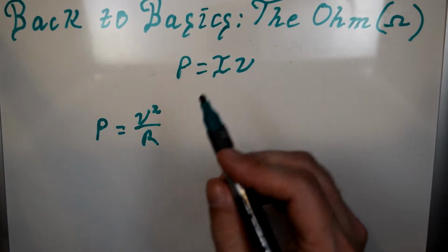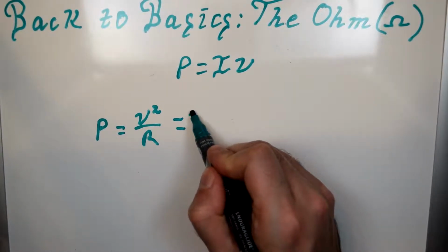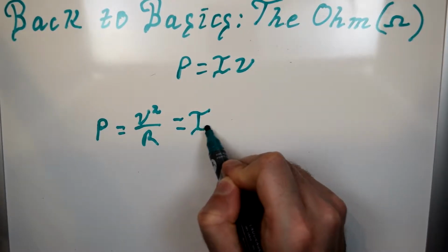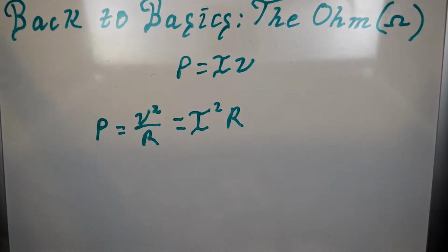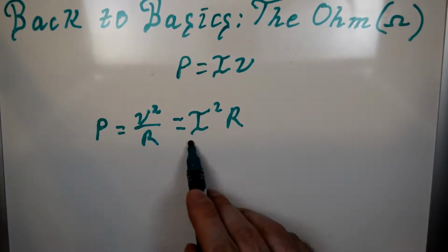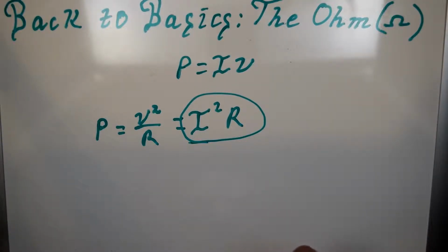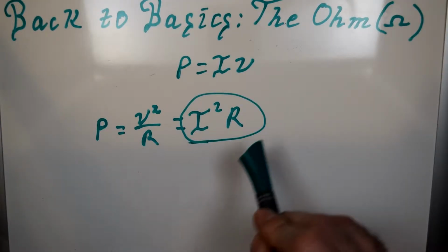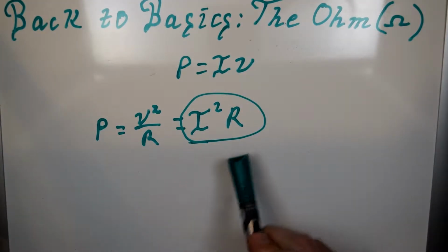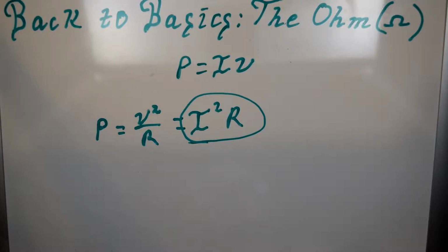You can also calculate power without volts handy by saying that power is equal to I squared R. I talked in the last video about the watt, about I squared R losses in electrical circuits or in electronic circuits and electrical wiring, wherein you're losing efficiency due to heat, and we colloquially refer to those as I squared R losses.